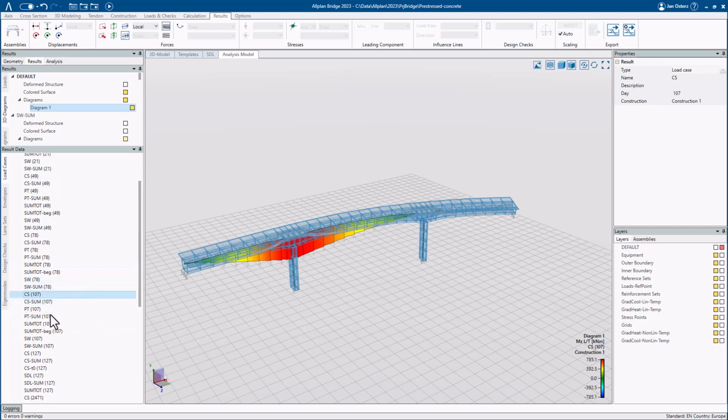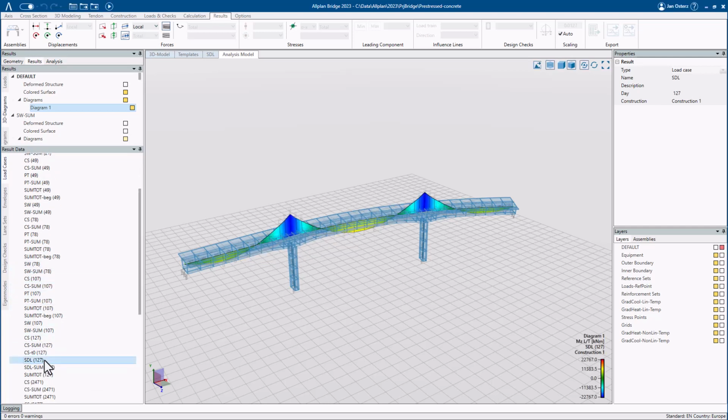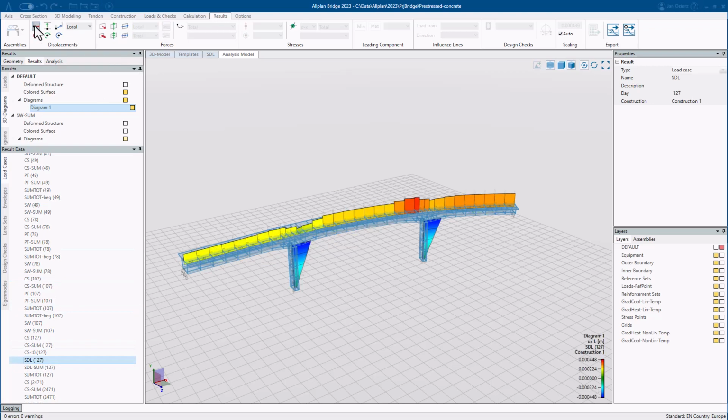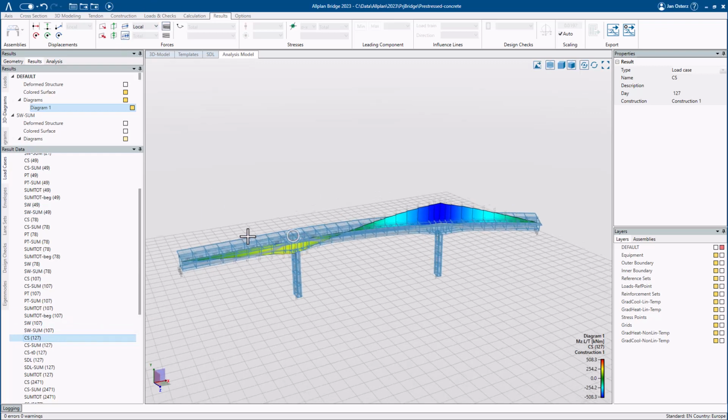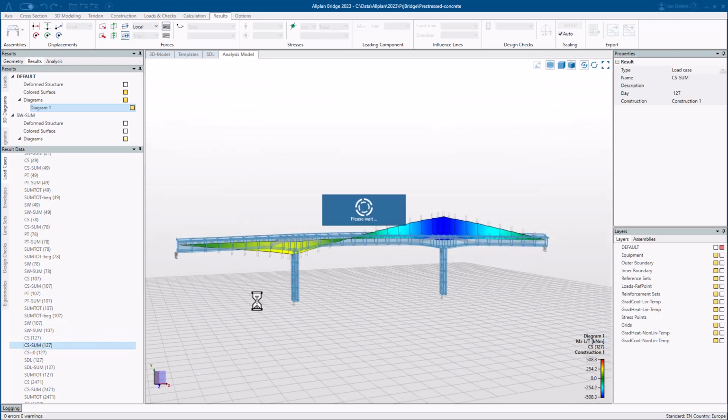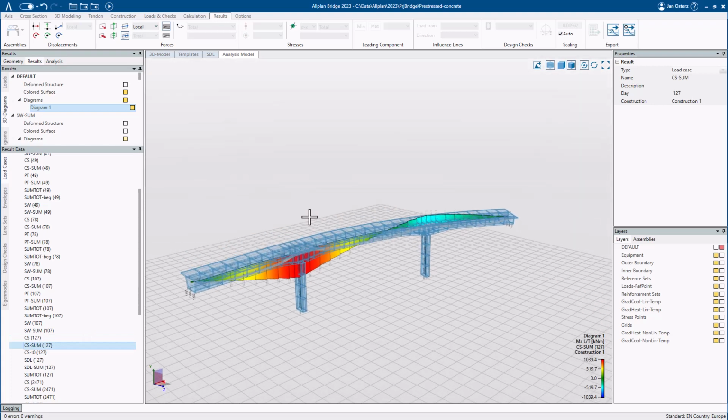And of course, what I have also mentioned is the STL load case, for example, that we basically have also an event for the creep and shrinkage load case at day 127, because some additional loads have been applied. And of course, for this also the creep and shrinkage calculation will change for its foreseeable duration.